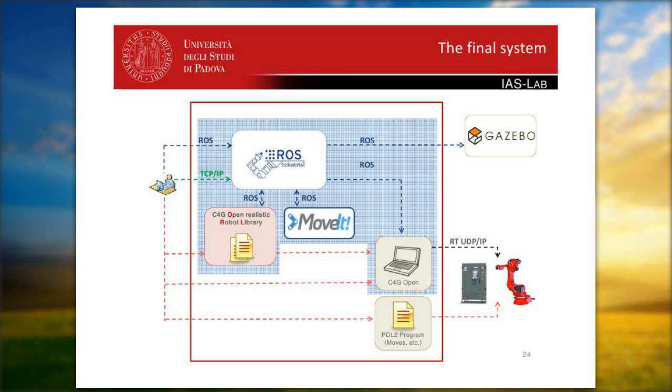Most existing systems use the producer controller for the real robot and different controllers for the virtual environment, because the robot manufacturer doesn't provide it. Instead, our collaboration with Fabrizio and with Comau allows us to use the same controller for both platforms. And in this way, trajectories are interpolated in the same way. So we use the same controller both for the real environment and for the simulated one.